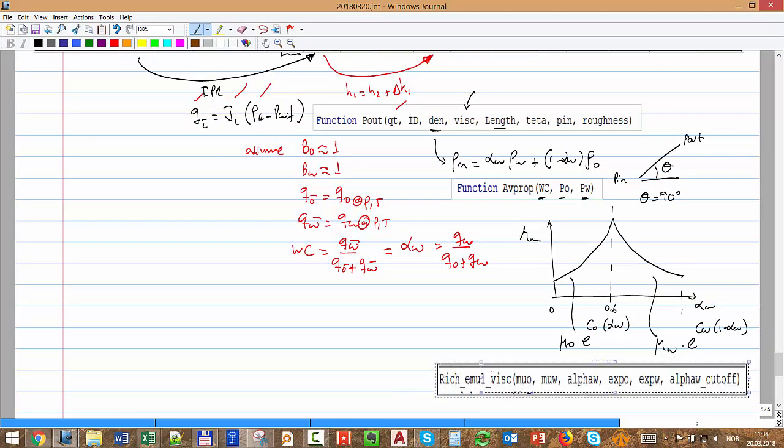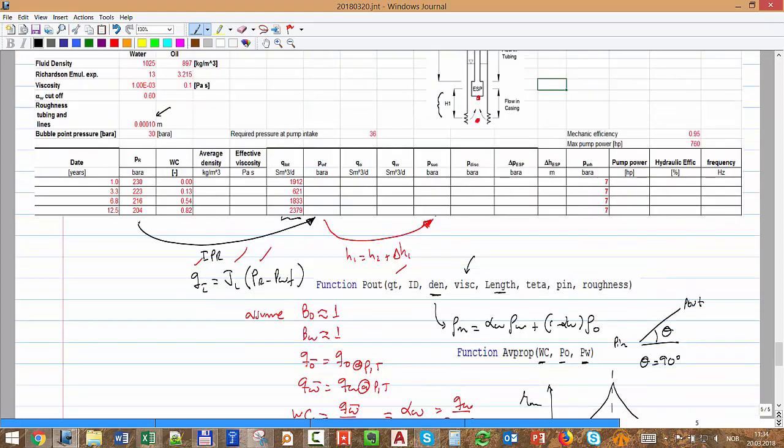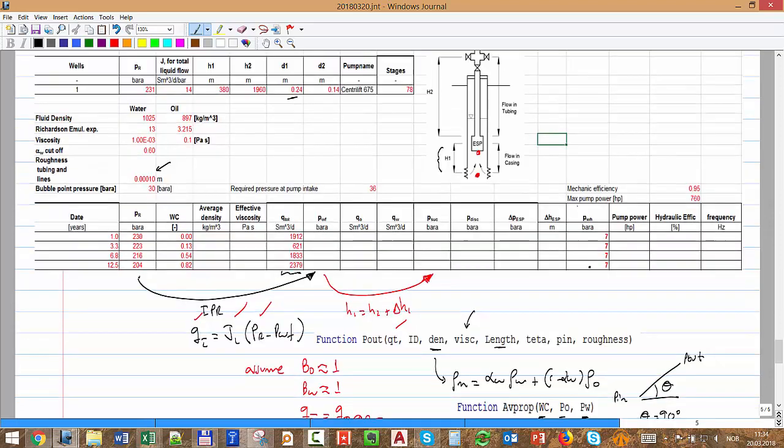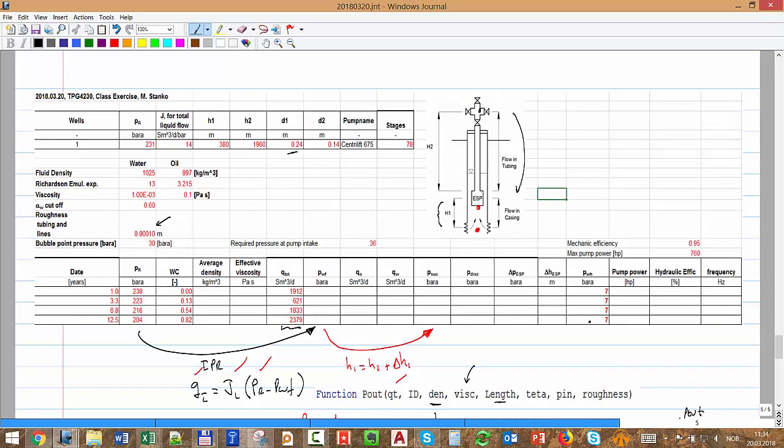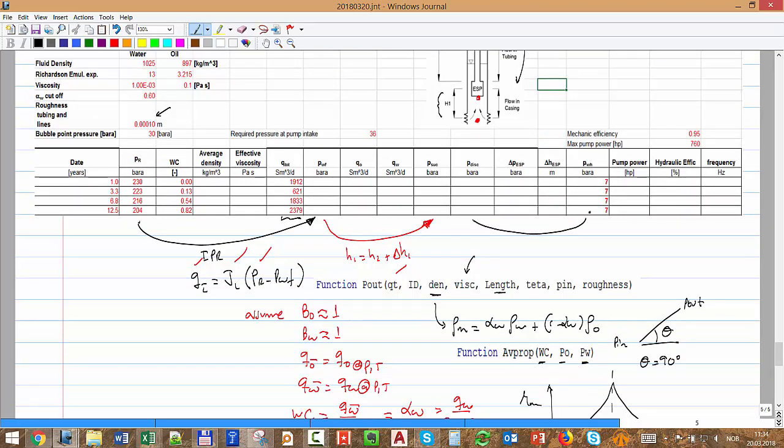And then, we can calculate very successfully the pressure at the suction of the pipe. What is the next step? I have to calculate the pressure required at the discharge of the pump to calculate the delta P of the pump. I said the wellhead pressure is kept somehow constant at 7 bar, and then I have to go from here all the way down to calculate the discharge pressure. I'm going to use exactly the same equation, the same input, the same viscosity, no change. Then I can calculate the delta P.